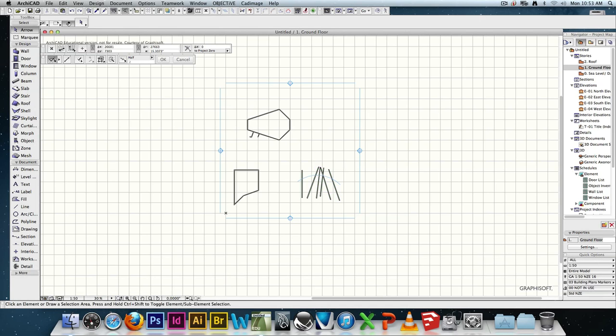Let's say this is all cool, but my design is kind of weird and crazy, and the ends of these walls are going to be red, and the ends on the other side of that arc are going to be white. There's not the option to paint part of the wall red and part of the wall white. What I have to do is split the wall on that arc and then paint one side red and one side white, okay? So what I need to do is split this wall.